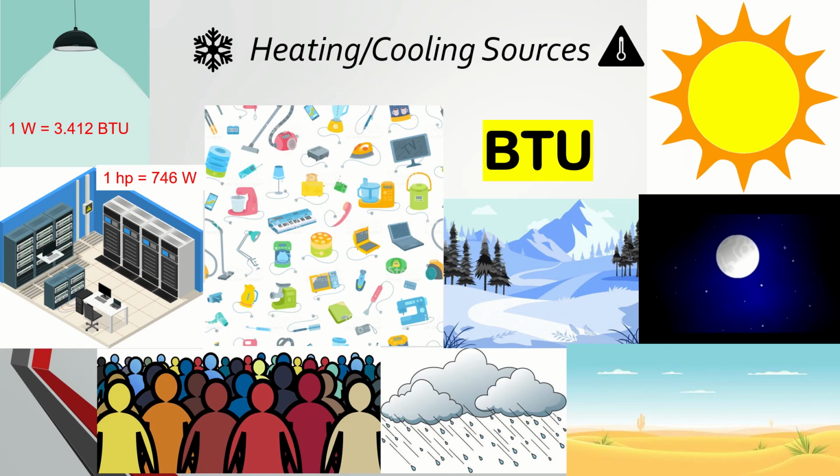So here are all or most of the heating or cooling sources in a building. There are things outside like the sun, lack of sun, weather. If you're inside, people emit heat, lighting emits heat, certain appliances or other equipment, which is often referred to as plug load. All of this adds or removes heat to the system. And the system we're talking about is the building. And we need to take all these sources and measure them in terms of BTUs.